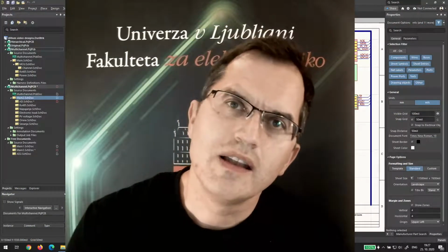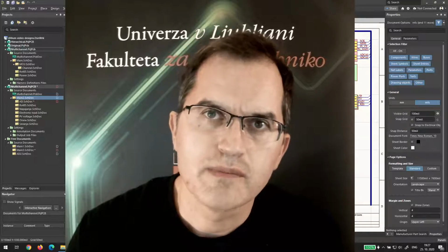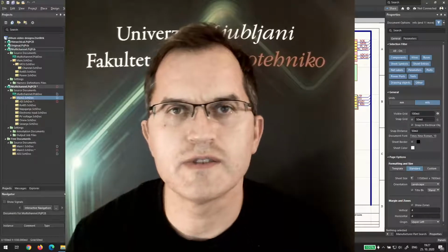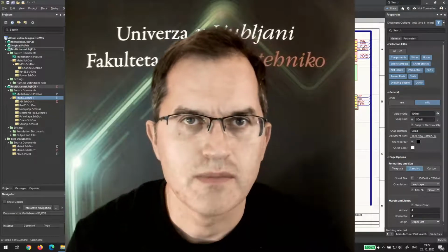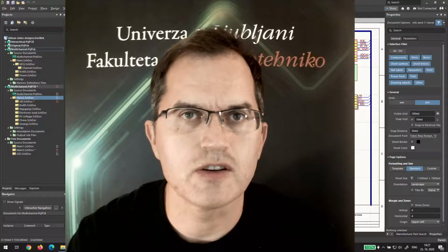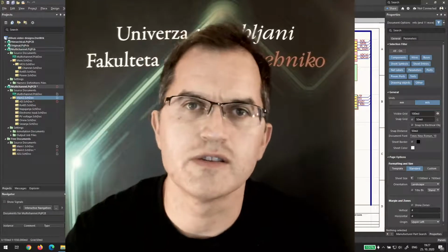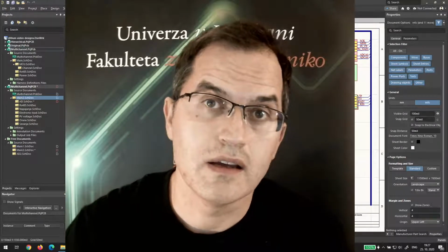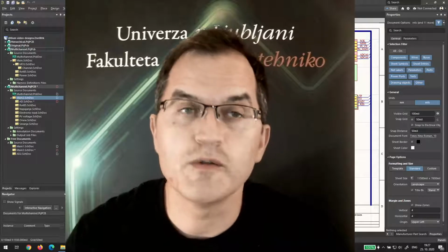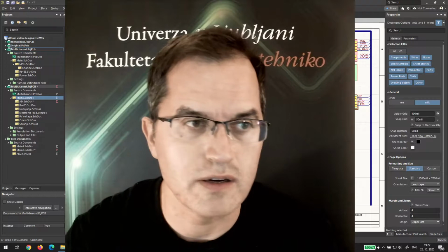Hello, let me show you how to use signal harness in hierarchical design. Sometimes we have a lot of signals that are a part of the same bus. They have a common function, and putting all these signals to all the ports that are needed to take them out of the block and put into another one might be a challenge. Therefore, we can group these signals into so-called signal harness.